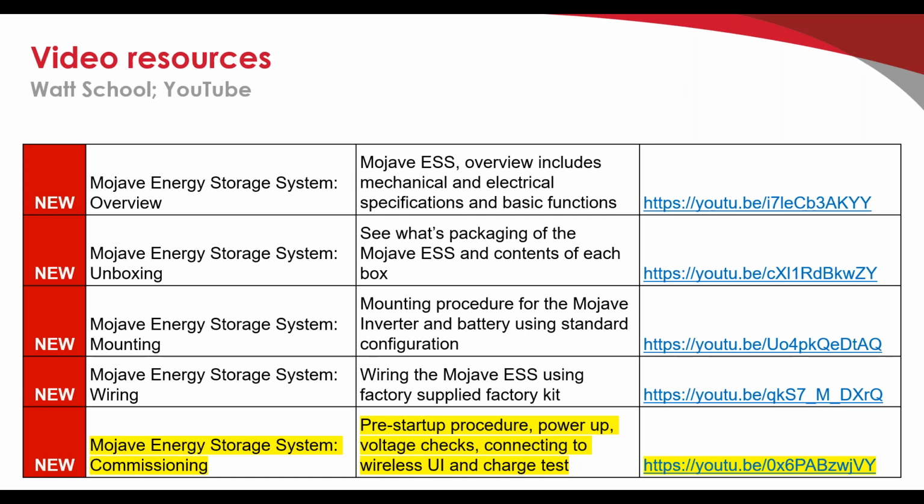Yeah, that's right. One of the things, to that point of being simple, is that as soon as I powered up the system and the BMS made communication to the inverter, the inverter auto-detected the battery. So there were no battery settings that I had to adjust whatsoever. I just went in there and basically had to adjust a few things based on my application, which made it way simpler.